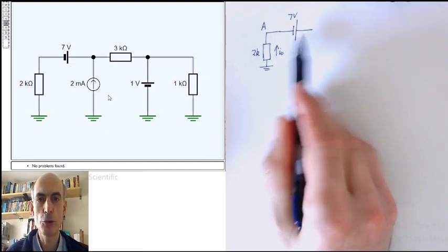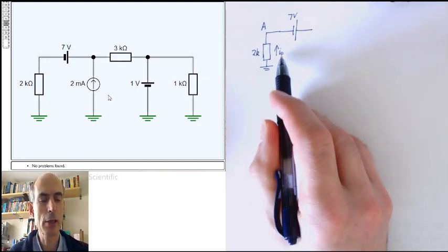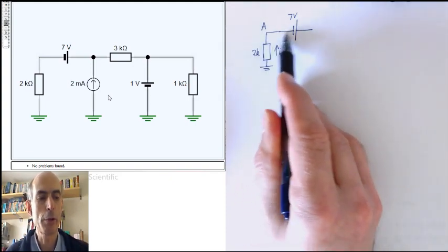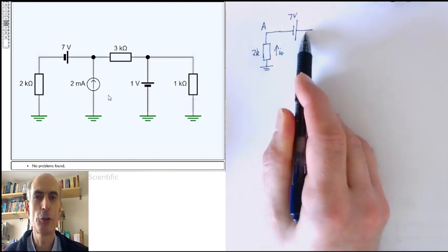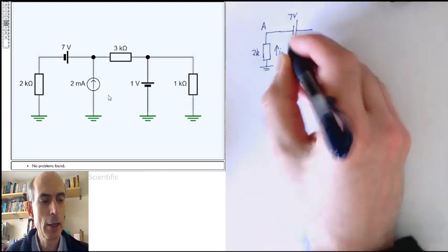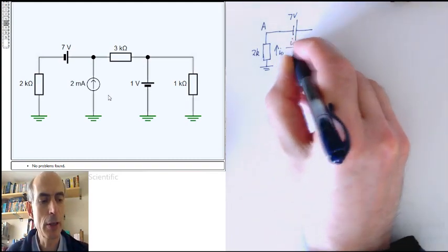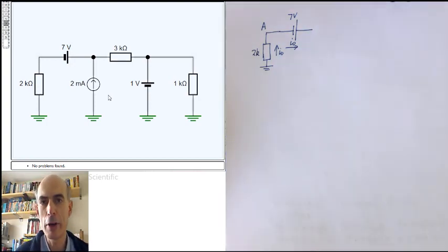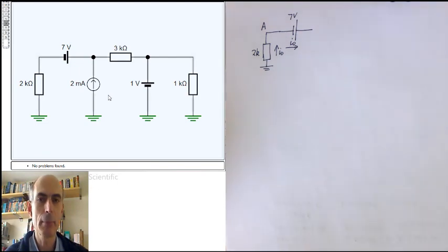However, I can short-circuit that process just by saying, but it's obvious that the current flowing up through this resistor will be flowing through this voltage source because it's got nowhere else to go. I can just define this current as being I0 as well. That reduces the number of unknown variables by 1. Good start. Every little helps.